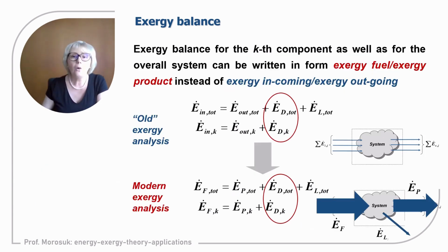Therefore, in modern exergy analysis, we are moving from the concept exergy in, exergy out, to the concept of exergy of fuel and exergy of the product. In this way, exergy of fuel and exergy of product are already cumulative streams. So we have only one stream of exergy of fuel and one stream of exergy of product, but in fact there can be many contributors to form these two cumulative streams.